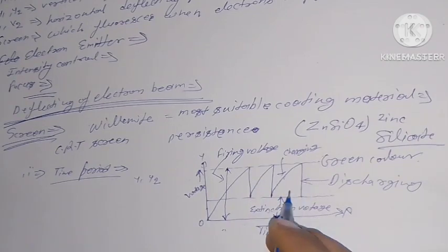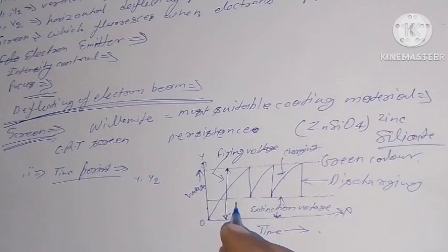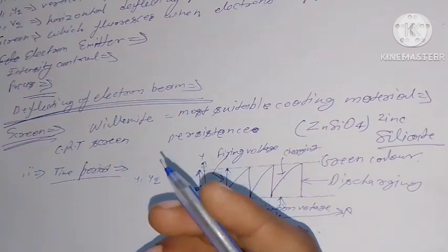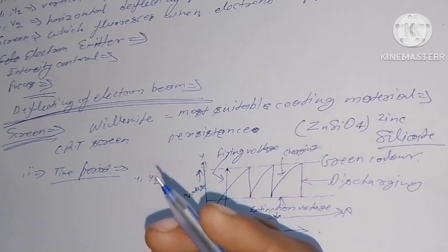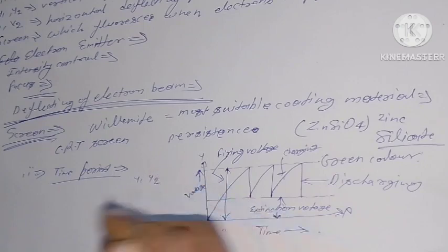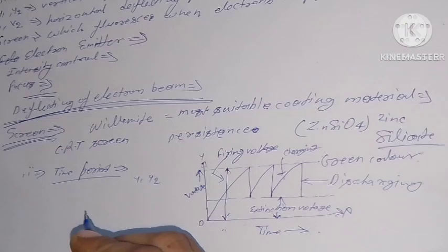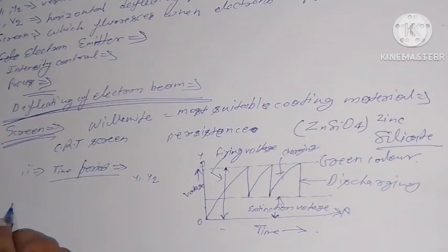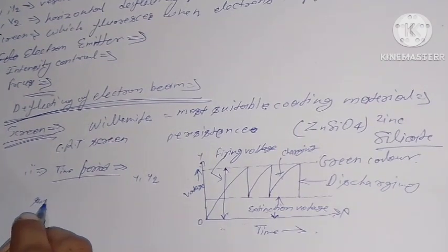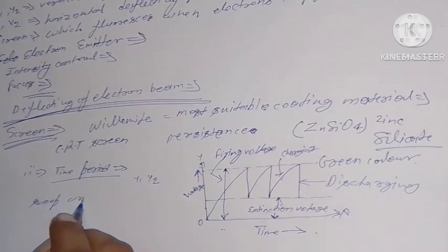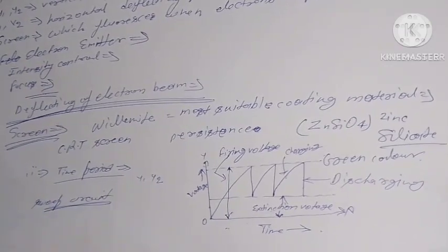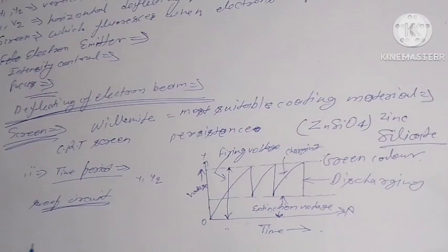It causes the beam to move horizontally across the screen at a uniform speed, and then snaps or sweeps back to its starting position. The electronic circuit producing the sawtooth voltage is called the sweep circuit, or time-base circuit.